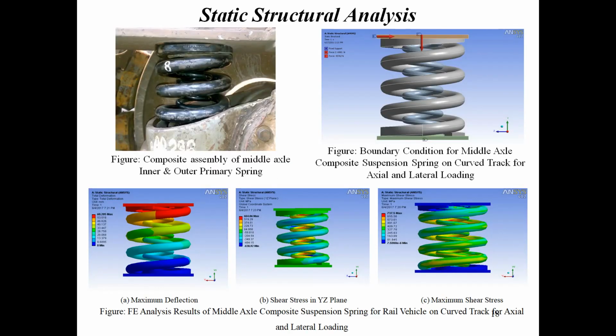These are some results with the help of static structural analysis. Static structural analysis is nothing but when the body is fixed at some point and the load is applied over that body, that is the static analysis. We will get a single result, not with respect to time. Okay, so whatever calculation we did in the design of machine elements is part of the static analysis. So you can try to solve those problems with the help of finite element analysis software.